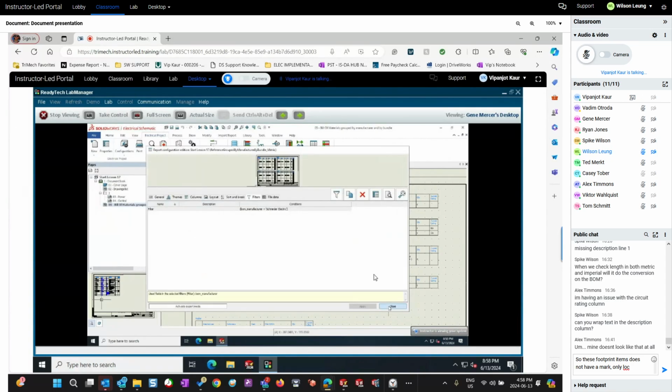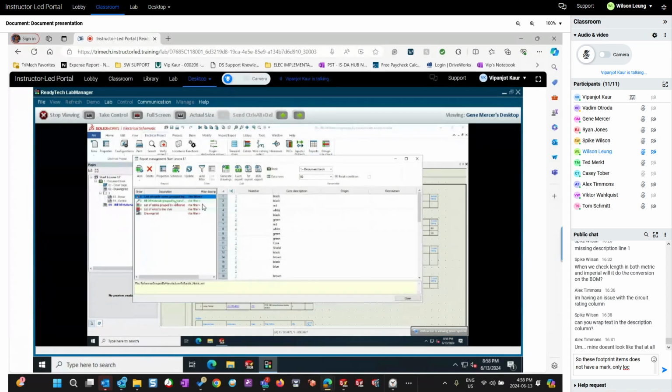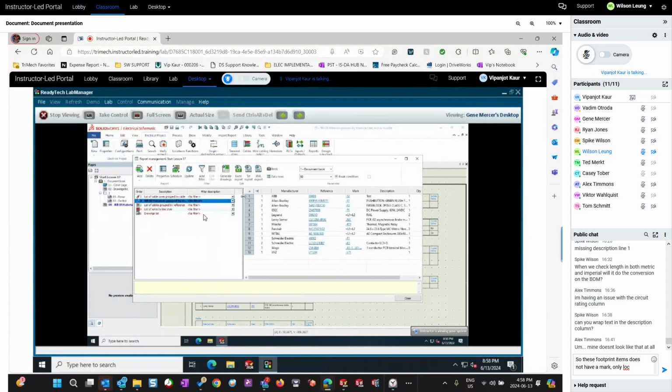So get to your project tab reports button, check the preview first. You can also update and check the preview. But hey, you cannot check preview and use filters here. You have to get back to the reports button. Good. By default, it's going to show you no filter. Expand this column. Check on your filter. Click on the filter button. Good. People are watching and learning, Jean. Thank you.